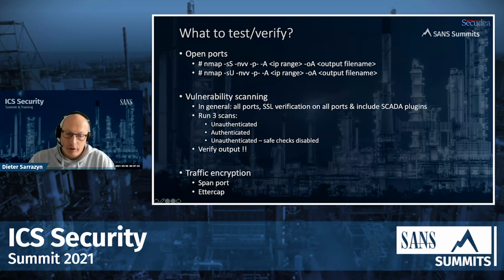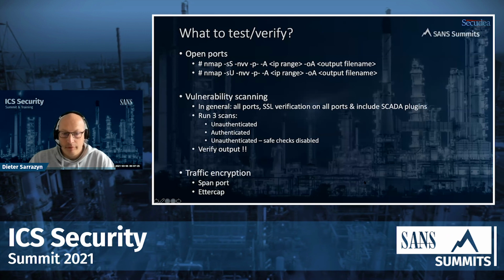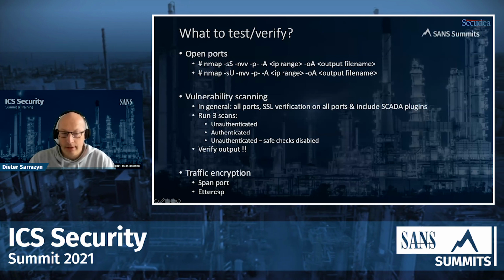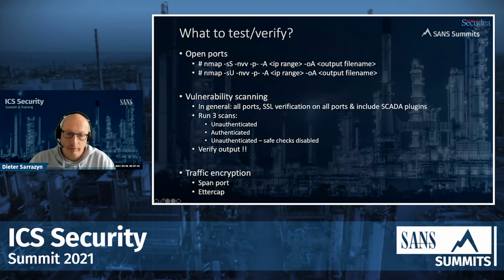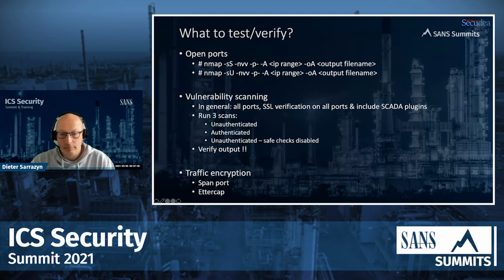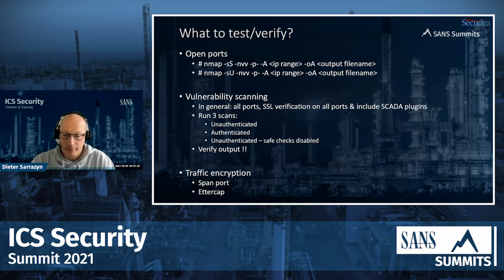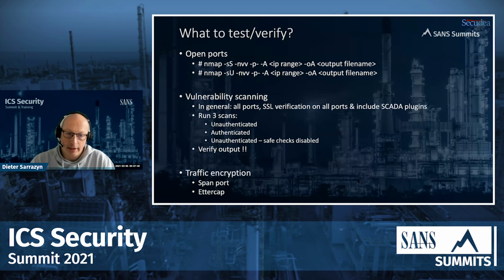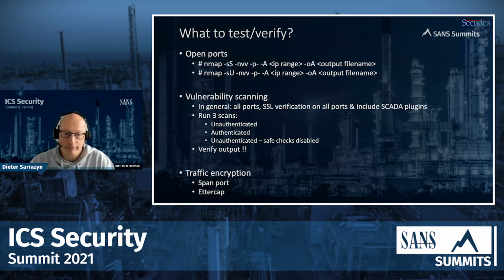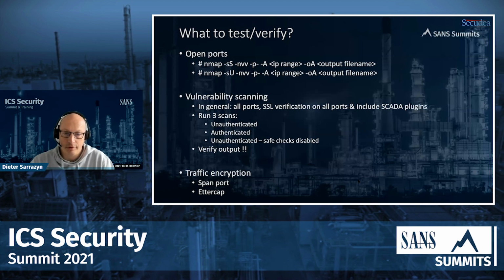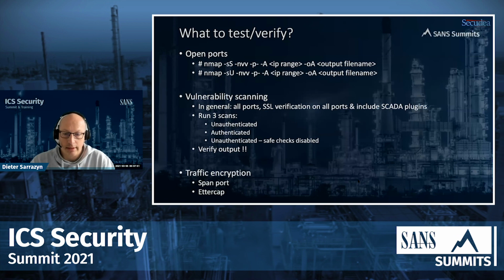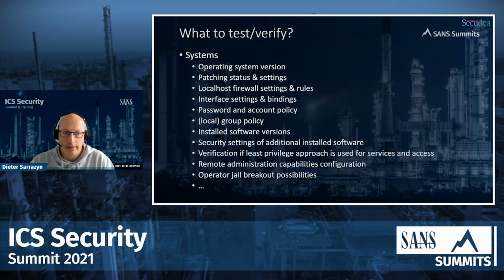To make sure you cover the traffic encryption point of view, if it's a managed switch, you can use span ports or you can use Ettercap or Bettercap to verify traffic encryption. Of course, most SCADA protocols like Modbus do not have traffic encryption yet, but I'm talking more about whether Secure Shell, for example, is used instead of Telnet. Is there SQL encryption and things like that? So it's important to look at.